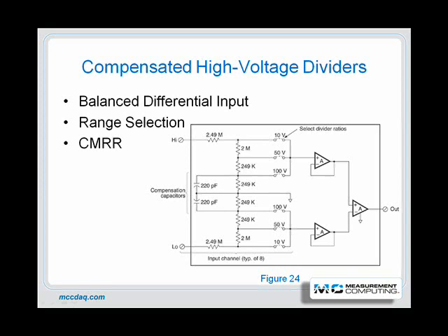Voltage divider ratios applied to DC voltages are consistently accurate over relatively long distances between the divider network and the data acquisition system input when the measurement technique eliminates the DC resistance of the wiring and cables. These techniques include a second set of input measuring leads separate from those that apply power to the divider, such as the Kelvin connection. Voltage dividers used on AC voltages, however, must always compensate for the effective capacitance between the conductors and ground or common, even when the frequency is as low as 60 Hz.